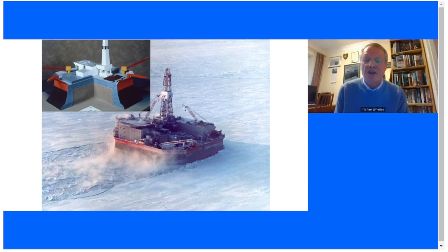It's a sand-filled structure. Now, at this point, I should also mention when the ice crushes, it causes a lot of vibration. Whereas in a severe earthquake, the vibration might go on for perhaps 10 or 20 seconds of severe shaking, with this platform, the ice can move past it for hours.